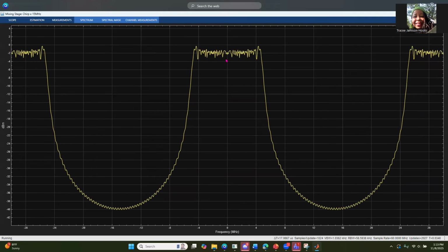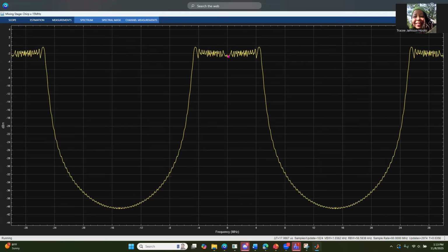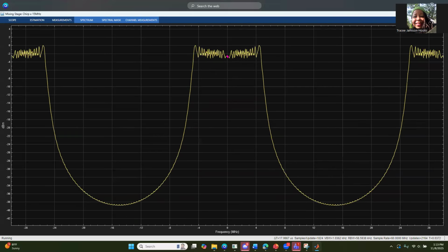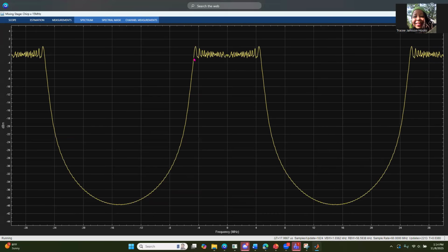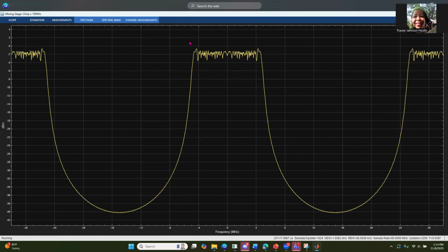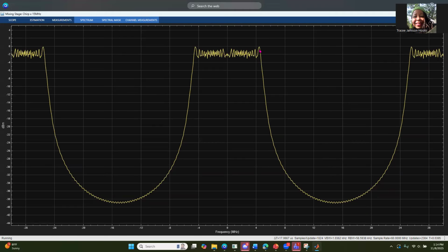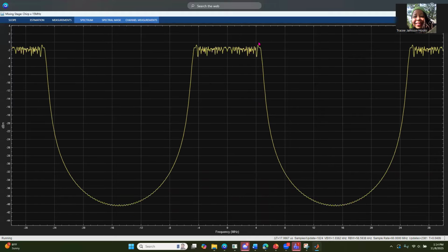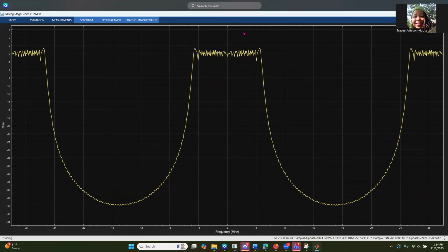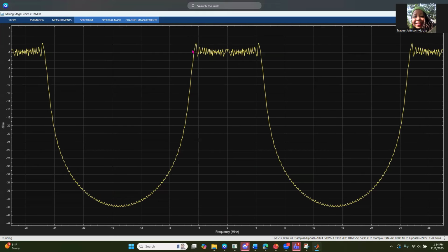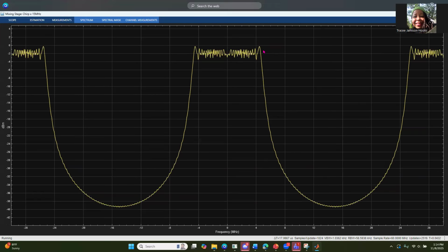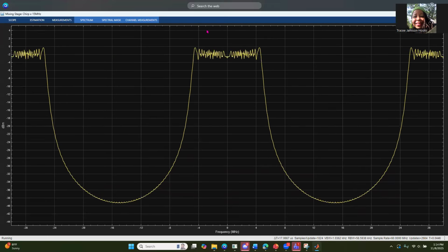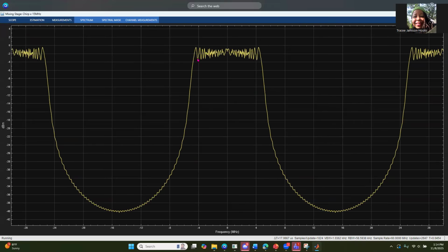So because we mix it with the 15 megahertz tone, that means that we have 15 minus 10 or 10 minus 15. So we're over in minus 5. And then we have 20 minus 15, so we're at 5 here. So this shifted the entire 10 to 20 megahertz tone down to minus 5 to 5 megahertz tone. Have the same bandwidth, same information, everything is shifted to baseband.